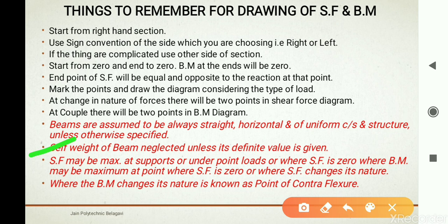Shear force may be maximum at supports, or under point loads, or where shear force is 0, where bending moment may be maximum. When shear force is 0, bending moment will be maximum, and when bending moment is 0, shear force will be maximum. Okay, so this is the point to be remembered. These red color points are very important.